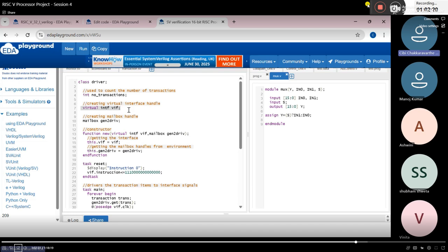It is also dynamic in nature and our class is also dynamic in nature. Finally we will connect all the virtual interfaces to the actual physical interface, and that physical interface will carry our data to the DUT. The final verification will be received through the monitor, and our monitor will check what data we are receiving, and our scoreboard will verify whether we are getting the expected data or not.